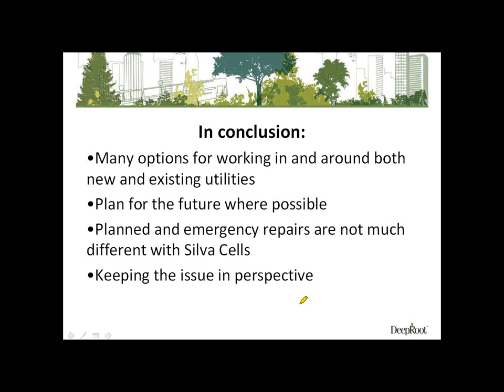I mean, it's been used on almost all of our installations, and so far we haven't had a problem. And I would just add that because the geogrid does go around the perimeter of the system, as Pat was saying, because roots taper quite rapidly, by the time they're at that furthest extent of the system, they're usually quite small. So we're not too concerned about it for that reason as well.